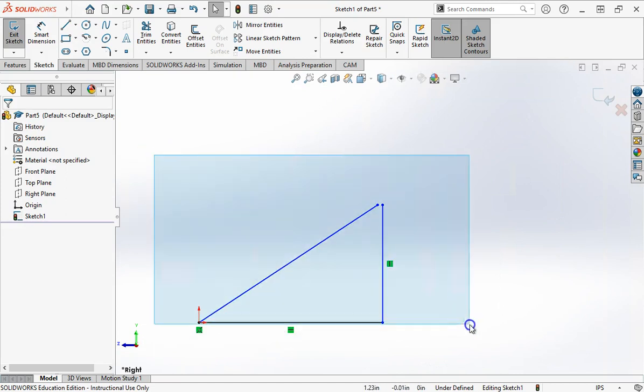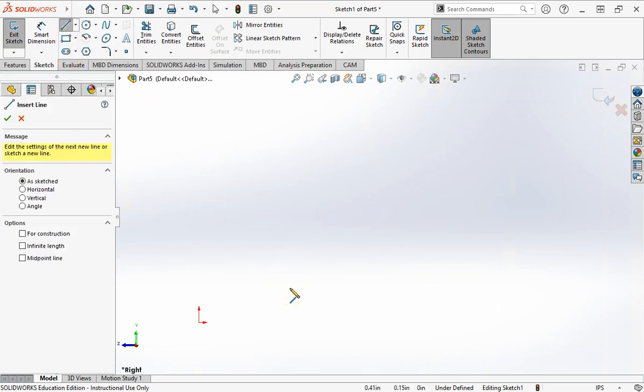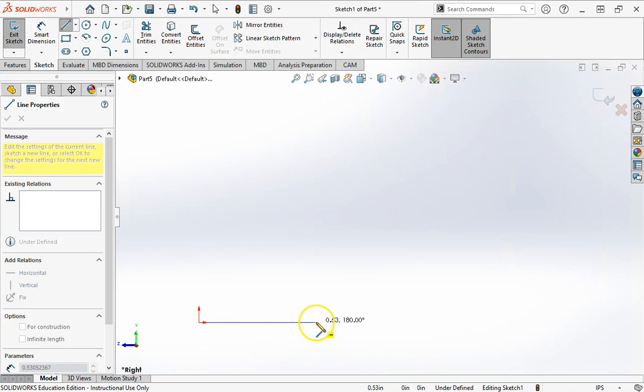The other method is where you simply click and release. The benefit here is that you lower the risk of creating those open loop sketches. If I just click and release, I've simply clicked the mouse button, and I'm not holding it down right now. You can see it's making the line. When I click and release again, you'll see the line is continuous. I don't have to go back to where I just finished and start a new line. The line that I'm drawing is continuous.